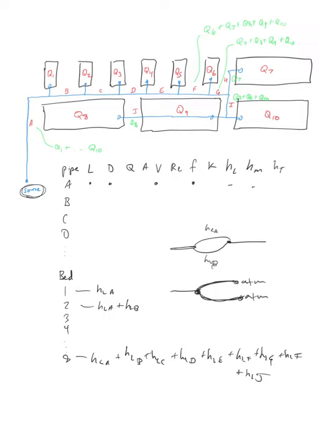And so what I think we're looking for here is we want you to develop this design tool where you can prove to yourself that the head you have available, however you're developing your water source, is enough to overcome the anticipated head losses in each of the branches.